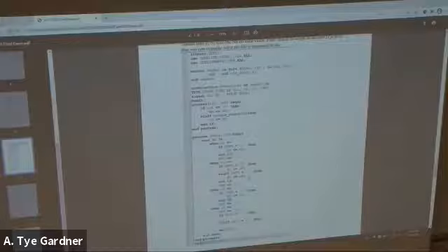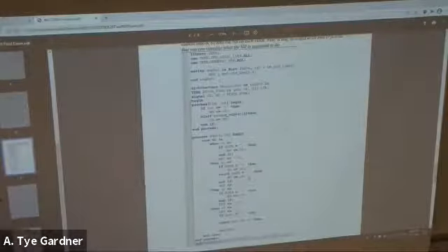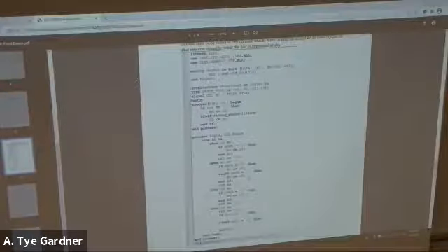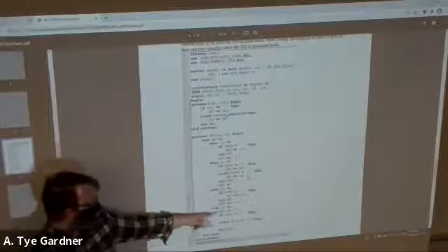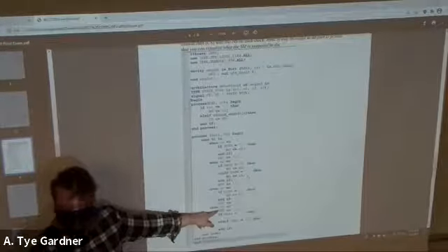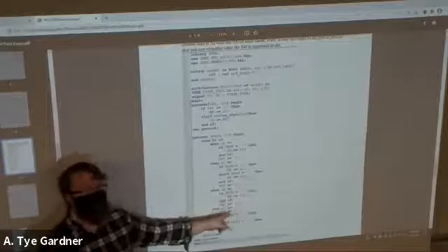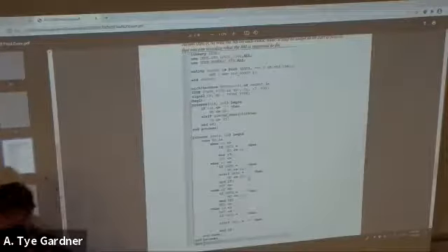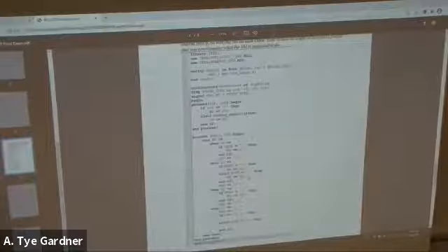How do I know? Well, the big giveaway is the number of states. It takes 4 states. The other giveaway is this detect. This detect says detect equals 1 without any conditionals, because that's the definition of Mealy versus Moore. In a Moore state machine, the output only depends upon which state you're in.